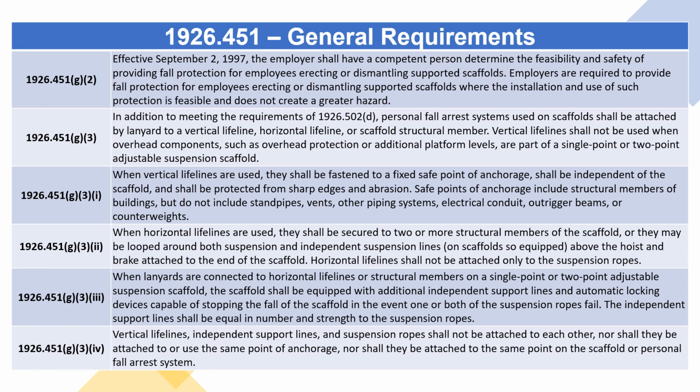Vertical lifelines, independent support lines, and suspension ropes shall not be attached to each other, nor shall they be attached to or use the same point of anchorage, nor shall they be attached to the same point on the scaffold or personal fall arrest system.